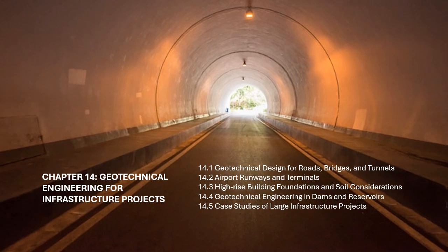The subgrade under the runway must provide sufficient strength to bear the repetitive and high-impact loads exerted by aircraft. Engineers assess the soil's bearing capacity through a variety of tests, including California Bearing Ratio, CBR, plate load tests, and standard penetration tests, SPT. The soil should have low compressibility and high shear strength to avoid excessive settlement and deformation.